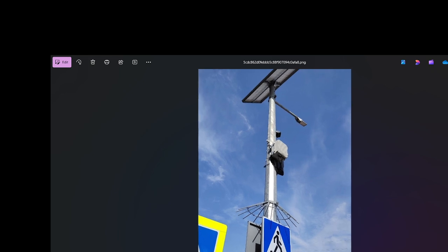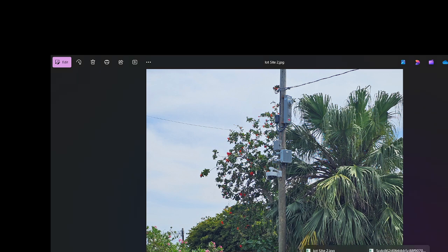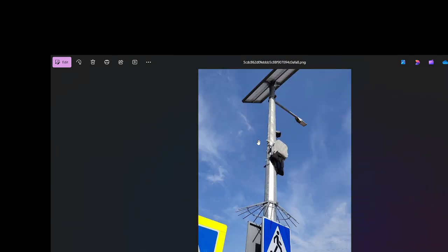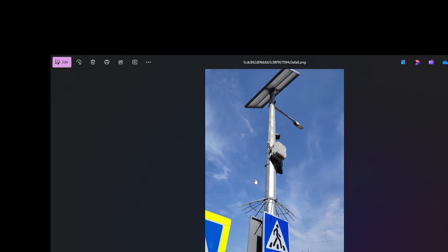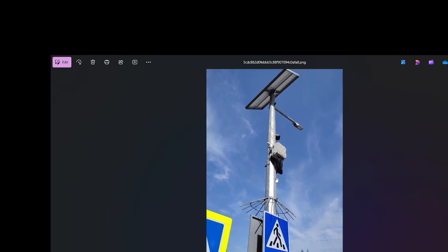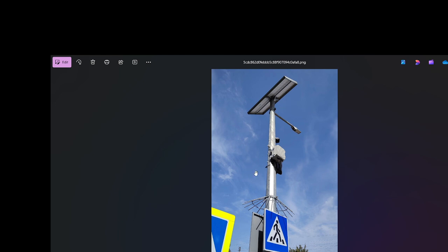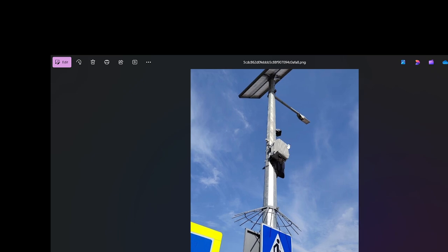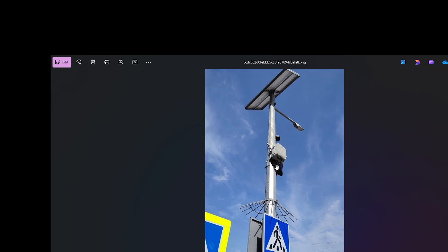You can understand that these two solutions are quite different and their requests are different, but we configure more or less the same type of IP65 IoT enclosure for them and configure everything inside. One special part I want to mention is that this site is in a very cold area, so we also configure a heater inside the lithium battery, to make sure it works fine in the winter.